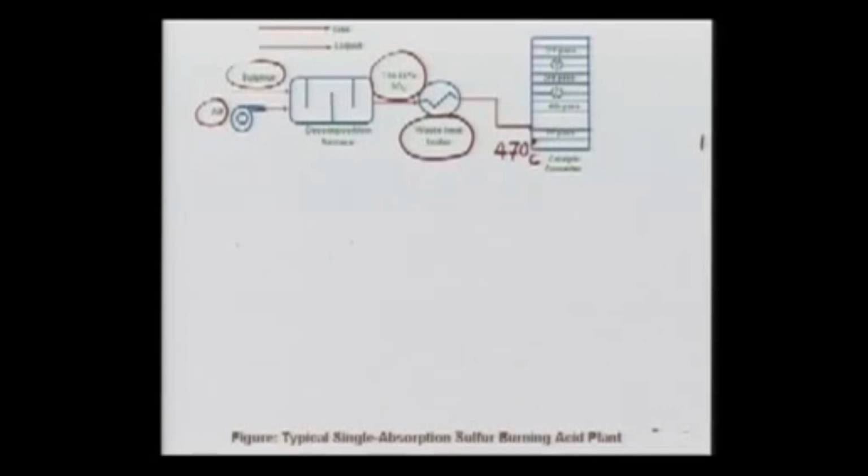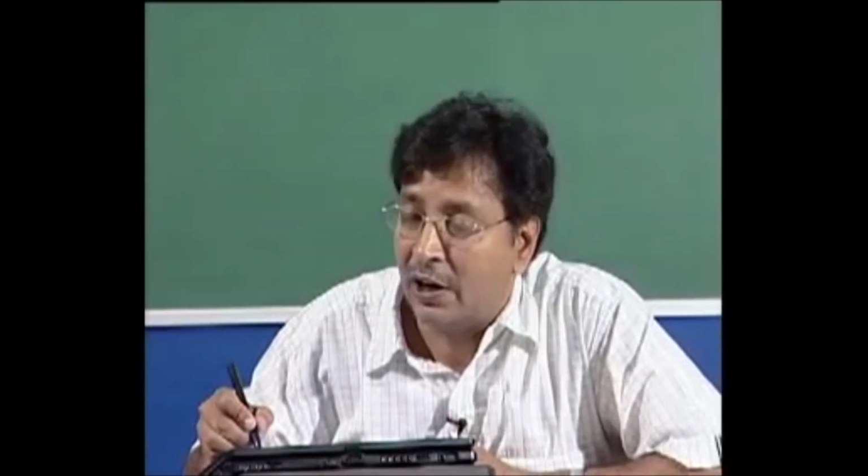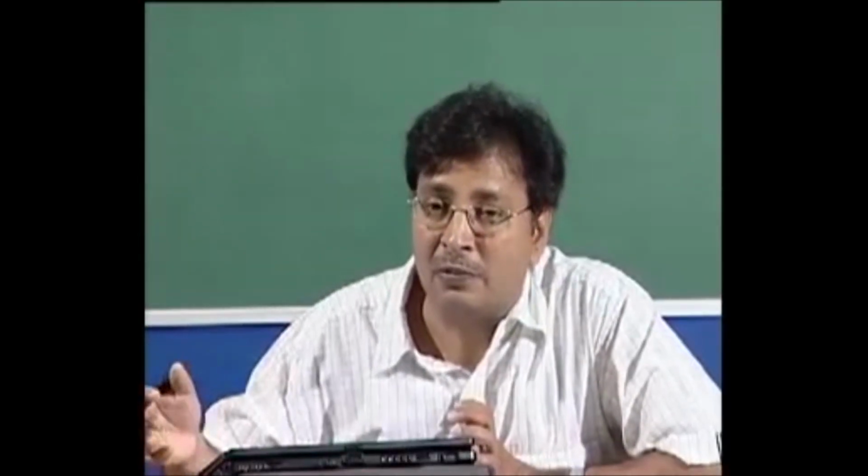You see here the first pass. In the first pass, the SO2 is immediately converted to SO3, and then, once the conversion is done, before it can go back to sulfur dioxide, because remember that it can, we quickly recover the heat. Once heat is recovered, the SO3 that has been converted will not go back to SO2, but there is still some remaining SO2.